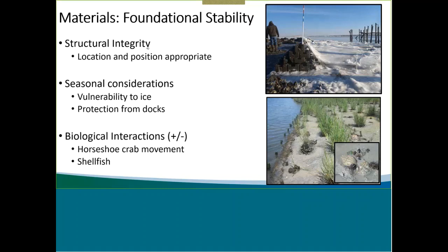Coir Logs, for example. In a more energetic environment, you do not really want a Coir Log to be your primary energetic defense. But if you are building a complex marsh terrace where you want to build up different elevations in different places so you can put different types of plants and create habitat complexity, I love burying Coir Logs. Bury them in the ground. You have something else as your energetic defense. Use these Coir Logs like Allison showed in her design to create this topographic complexity.